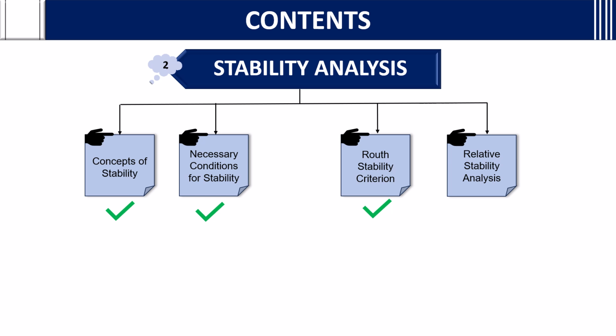is that the main characteristic equation in terms of s, you will substitute 1 by z in place of s, and take the LCM. For that z plane, you will write the Routh criterion. So you should practice anyway. It will take time. If you practice only, you will understand. So by this, I stop the video here. Use the Routh stability criterion.